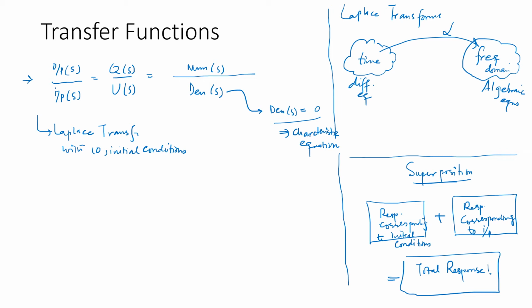Coming back to the Laplace transformation, I should also emphasize that in the time domain, for example, if we are going to use the d by dt operator, the differential operator, that is going to be transformed into the S operator, and that's because the Laplace transformation has been taken over here.